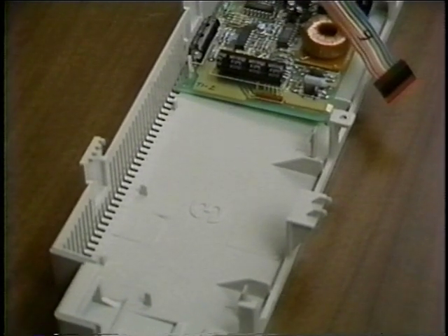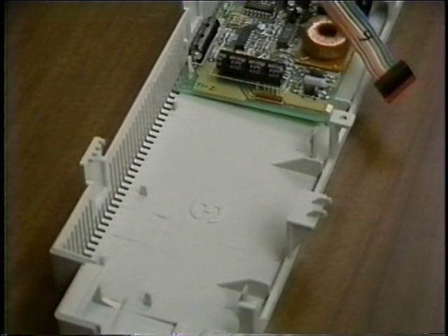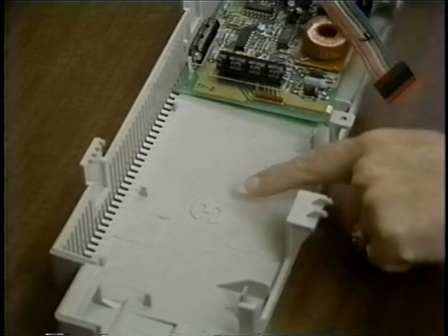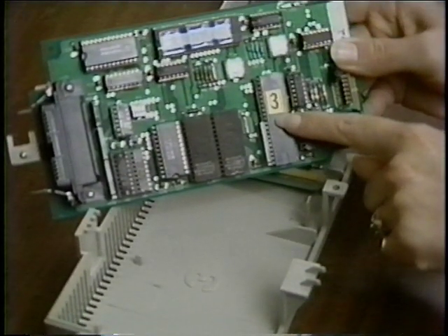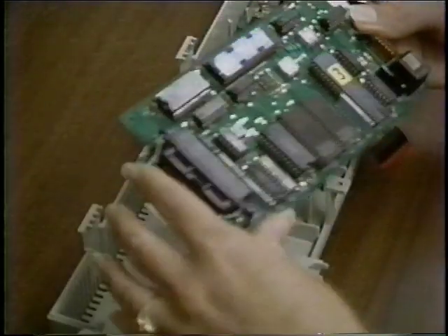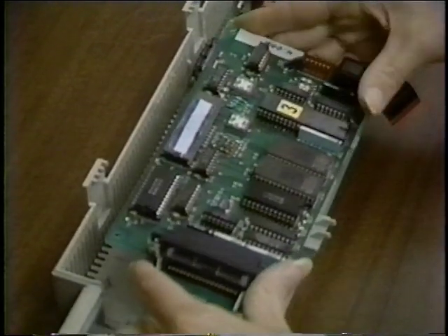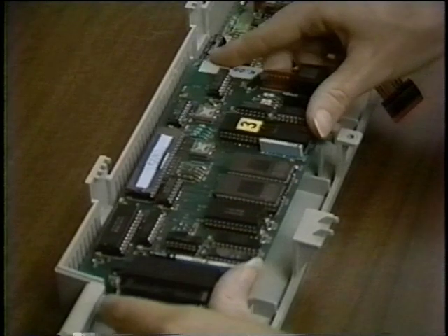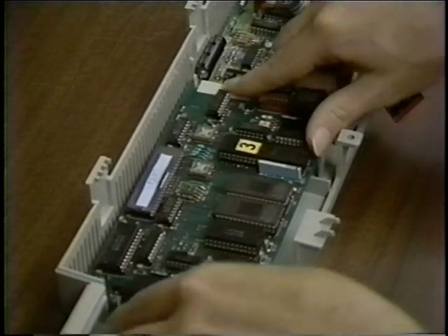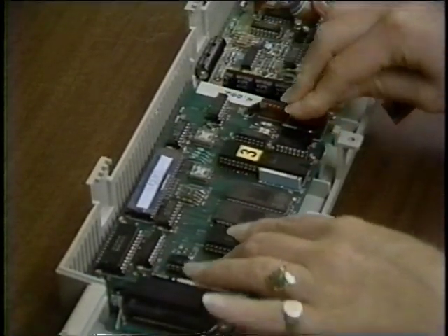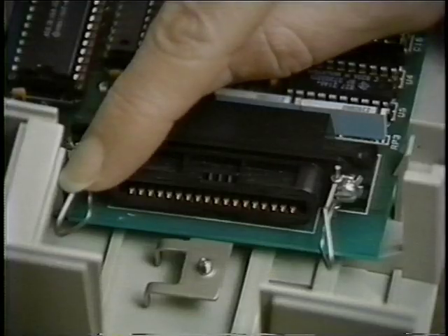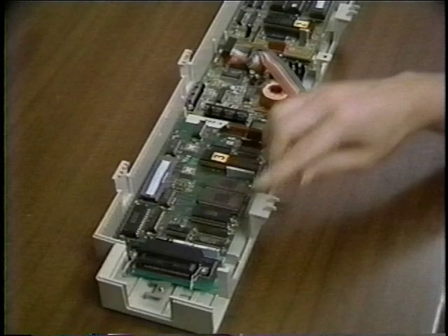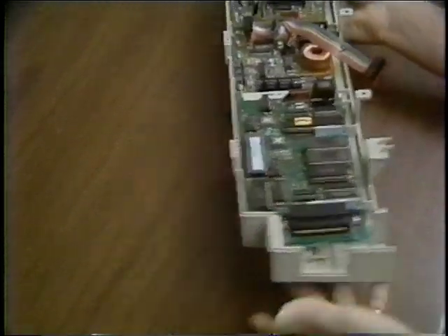Board 3 is installed in the area marked 3 using the same method to install board number 2. Remember that board 3 can be the display option, the printer option, or both. Be sure the two locking rings on the printer cable connector are not trapped inside the options cover.